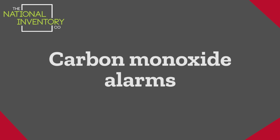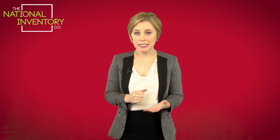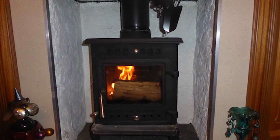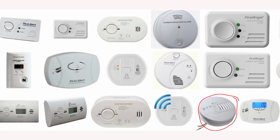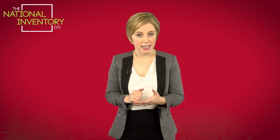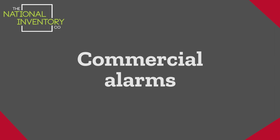Carbon monoxide alarms. Carbon monoxide alarms are legally required in any room where there is a solid fuel burner, such as an open fire, wood burner or an oil burner. Carbon monoxide alarms can be hardwired or battery operated, and you will be required to complete a push-button test and a gas test to ensure that they respond to gas. If you haven't already fitted a carbon monoxide alarm in your property where there's a gas-based appliance, such as a gas boiler or gas hob, you will be required to do this.